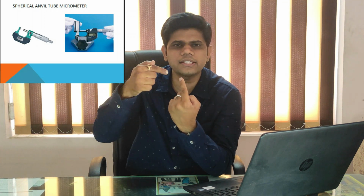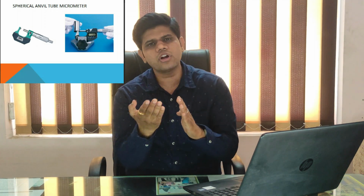It will be directly in touch with the wall, in the radius, and you will get the exact wall thickness. There will not be any gap between the surface and the job profile. So you will get a very good result while using this spherical anvil tube micrometer.